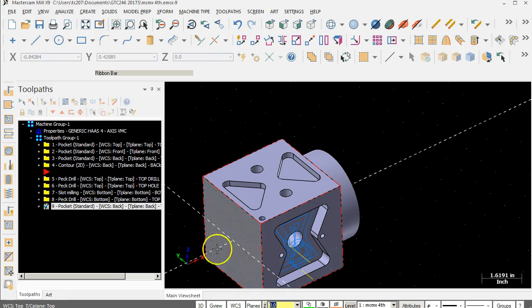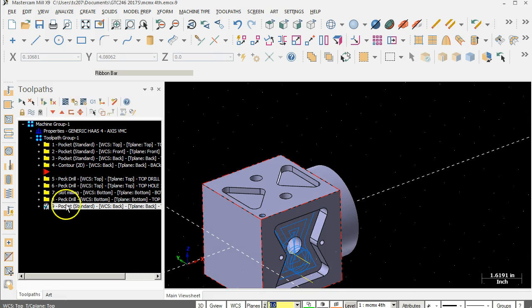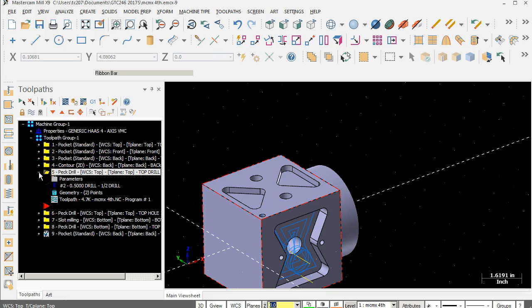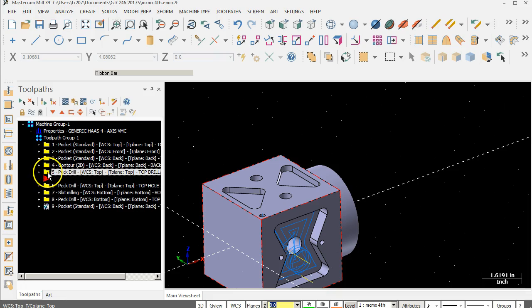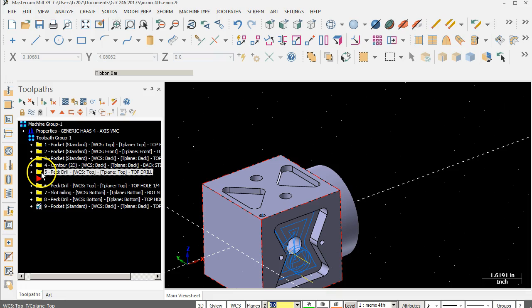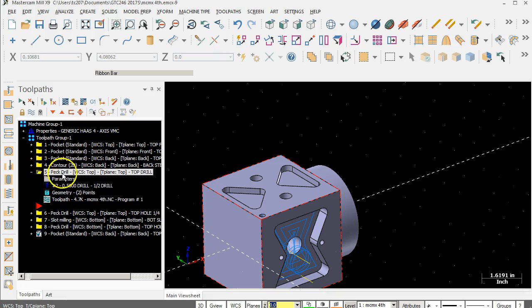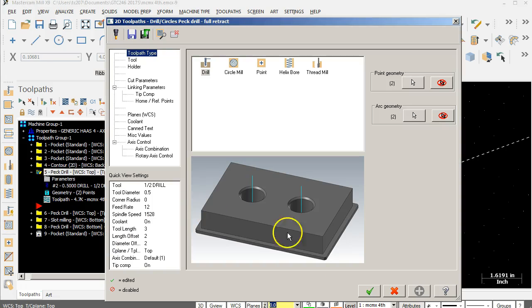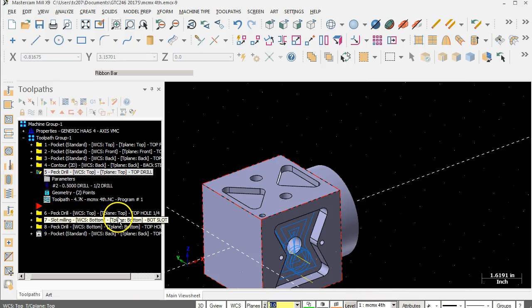All right, a 3/4-inch tool pecking directly is going to generate a lot of tool pressure if there's not a pilot drill. All right, so double check and make sure that that's the only one. There we go. Keep jumping on the wrong one.